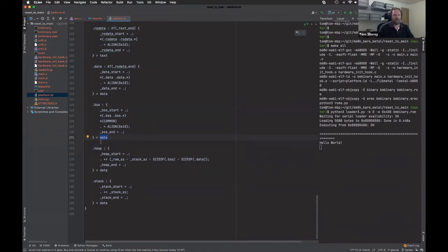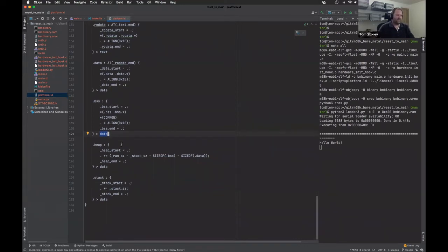Usually what you would find, and it could be implementation specific, is that the BSS section would basically be zeroed out at start. So anything that you allocate but don't give a value, and if it's not on the stack, would basically start off with a value of 0. But it's one of those things that you might want to test if you were using somebody else's tool chain, just to see what they actually do with a value that is uninitialized.